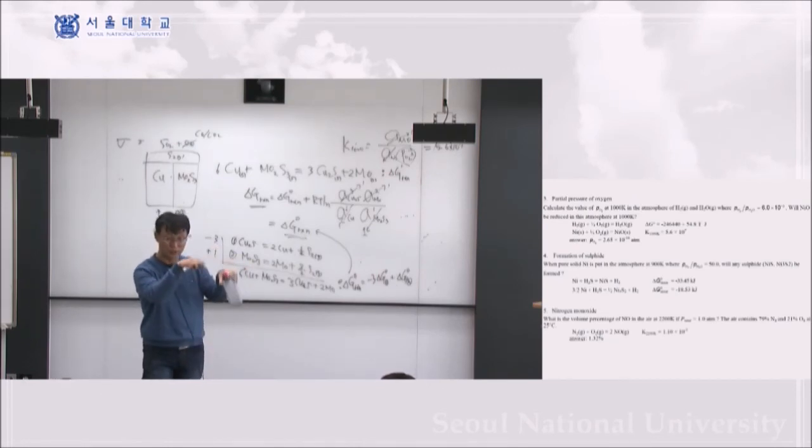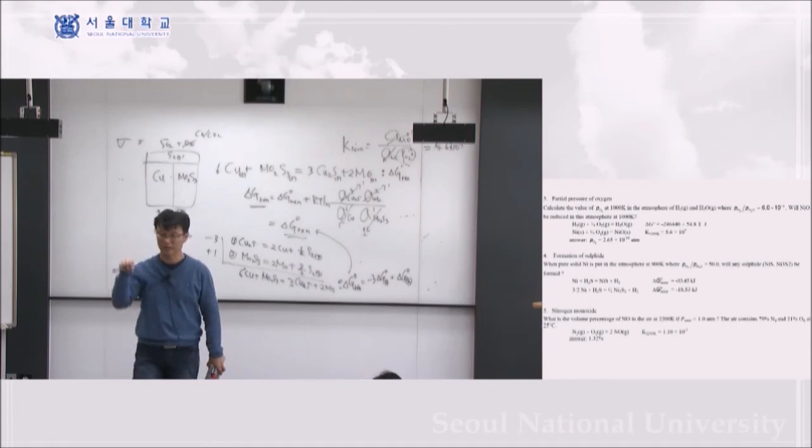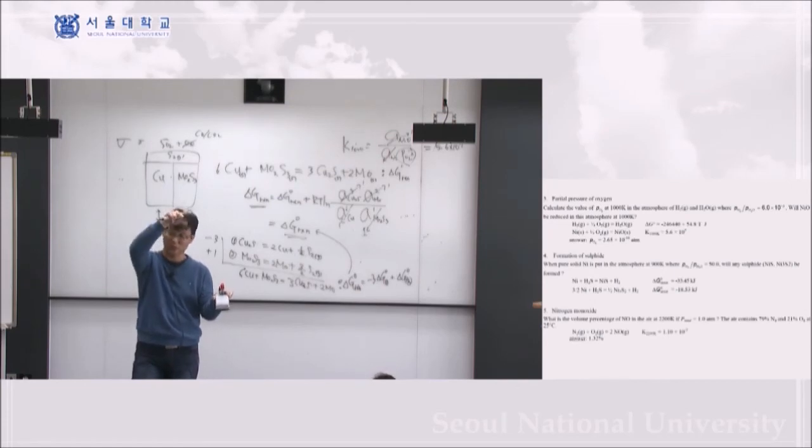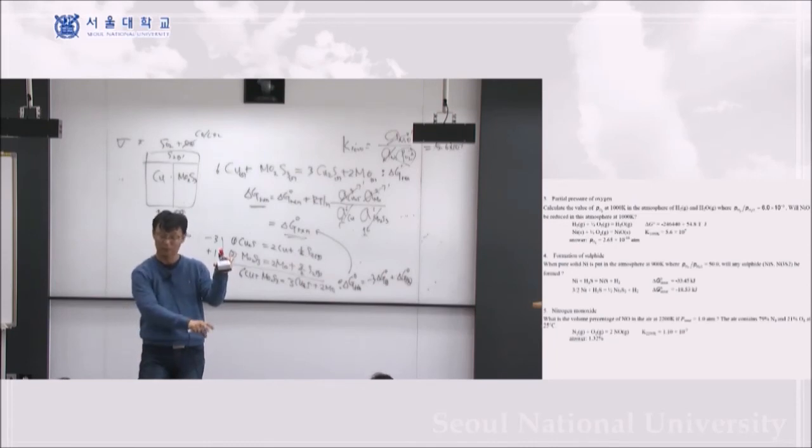And then you have to compare these two values: the actual partial pressure of oxygen from the gas, H2 and H2O, and your virtual partial pressure of O2. If the actual gas pressure is higher than your equilibrium virtual partial pressure, then you're going to have oxidation, so nickel oxide will be stable. If it is lower than your virtual one, then you'll have reduction, so nickel oxide becomes nickel metal. That's what I showed you as number 3, the third possible way to calculate question number 1.